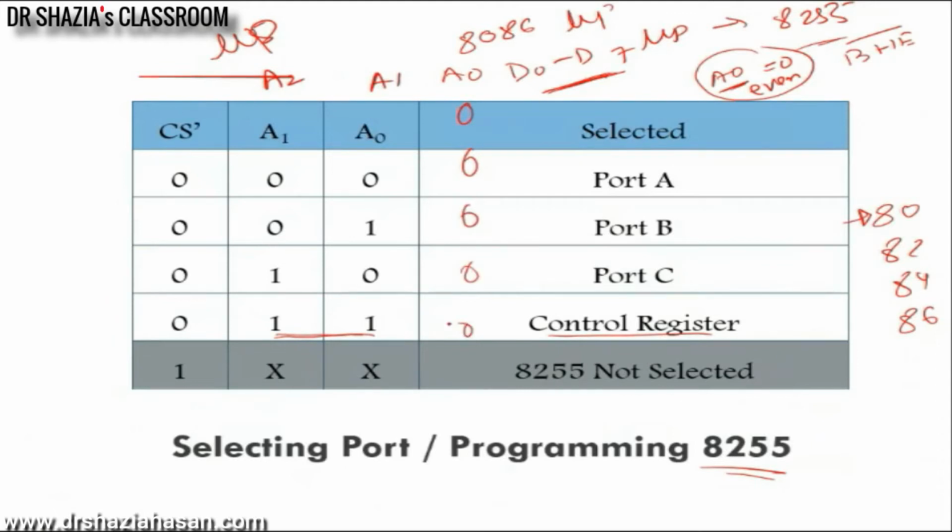Now I am telling my base address is 80. The port address is an 8-bit address; I am using an 8-bit address, fixed addressing mode. You can go for variable addressing as well. My first port address or base address is 80, so the first port address generated should be 80. Written out, 80 is 10000000, which is A0 to A7.